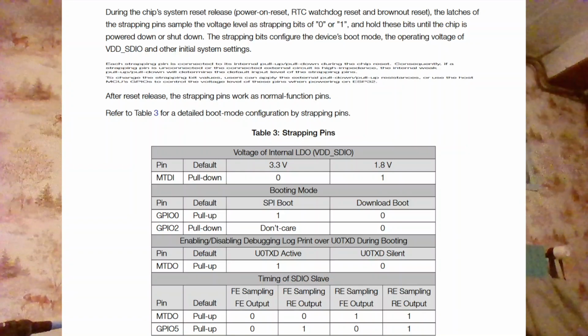And in the table, you see under booting mode that the GPIO0 pin, if it's driven to 0, triggers a booting mode of download boot.